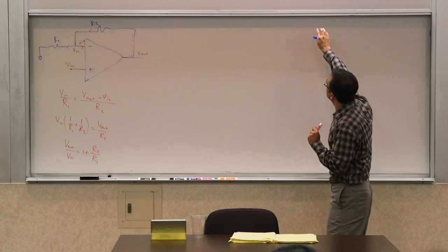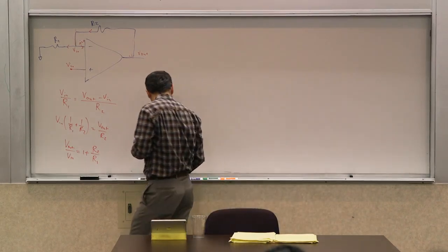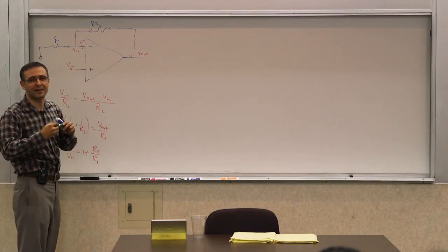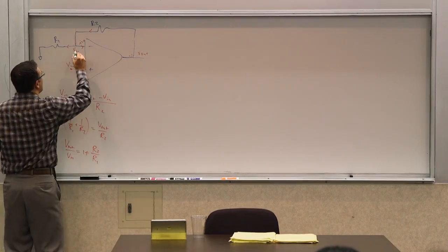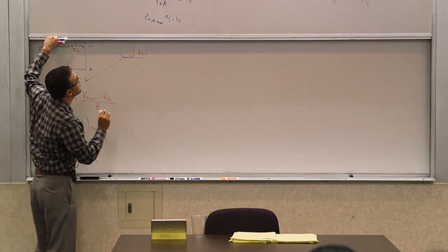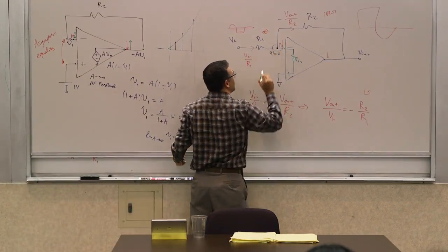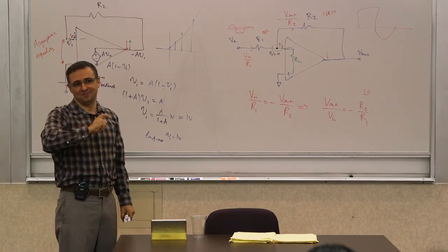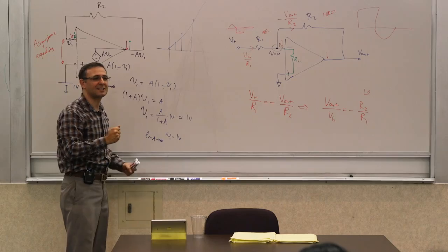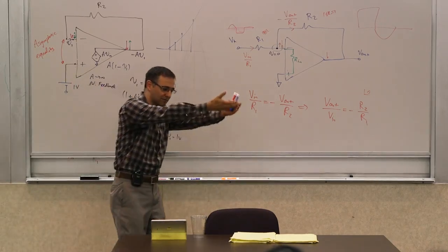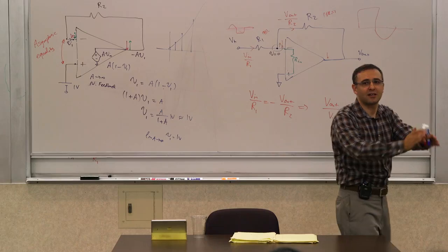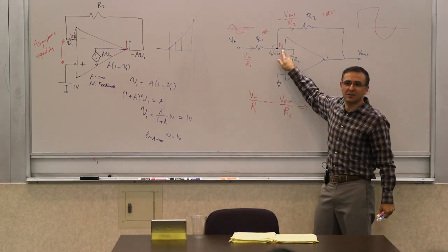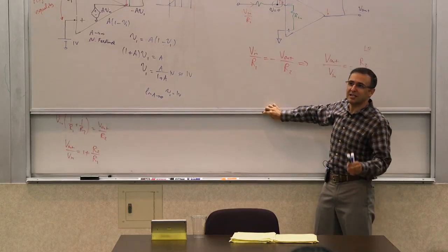So remember, there's something interesting that happens at this node. This is one of the fundamental concepts of electrical engineering, and even a lot of electrical engineers won't articulate it this way, but you will be from now on. This node is very powerful. We call it a summing node. It's like a bank. Everyone pours the currents in there, and it just makes sure that they are all equally added, and it doesn't tax it at all, or very little, because of this feedback, because of the A. So it's a really kind of perfect bank,